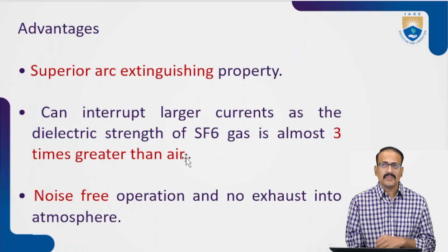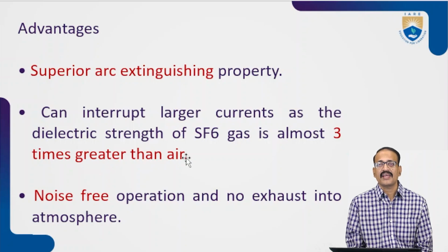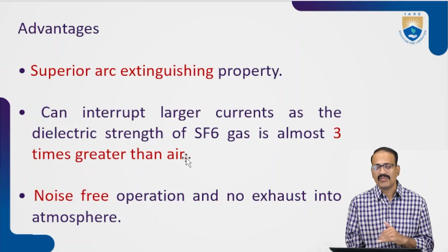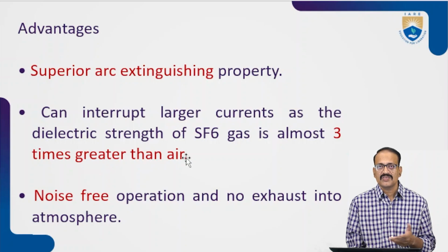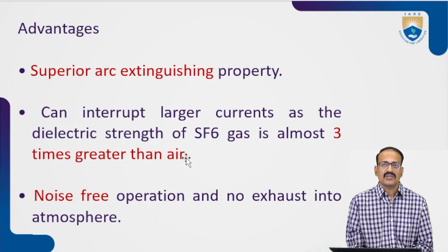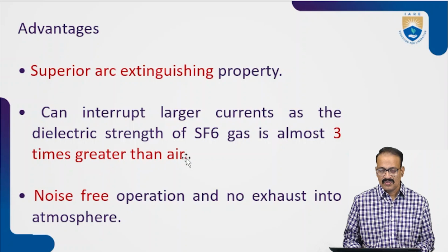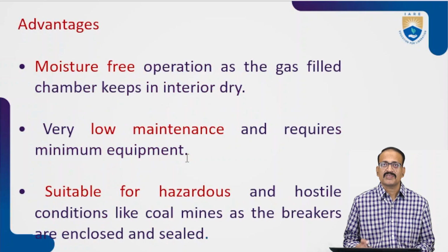It can interrupt large currents as the dielectric strength of SF6 gas is almost 3 times greater than air. So the dielectric strength is also greater when you compare it with air. Here there is no noise, and no exhaust into the atmosphere.